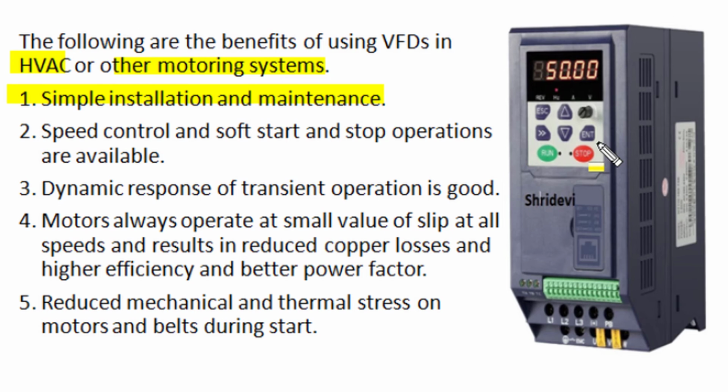Modern VFDs have the facility of not only speed control as required in motor operation, they can also provide soft starting and soft stop operation as required. The dynamic response and transient operation of a VFD is also very good. So in case of fluctuation in supply voltage or in mechanical loading conditions, the VFD can adjust its operation and maintain